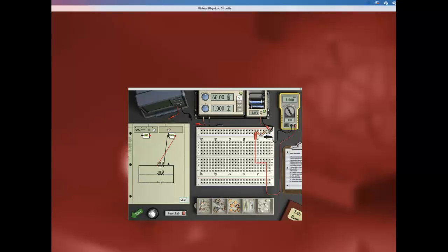You have to add them and divide by 3 to find the average. From step 6, you are going to add voltage AB to VBC. Then this is your calculation. For parallel circuit, from step 5, add currents IAB and ICD. And from step 6, calculate the average of the 2 voltage measurements.